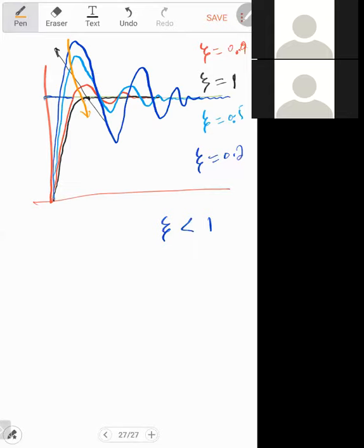So this means that we can do this by increasing the damping, but if we increase damping to a higher value, to this value, what will happen? The rise time will increase, so the system response will become slow. In simple words, the response will become slow.